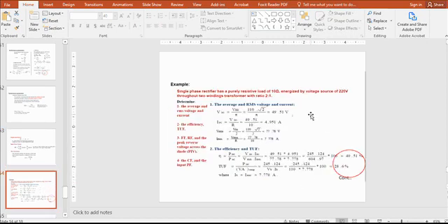Now this is the formula. We can see that the average and RMS values are calculated. VDC is equal to Vm over pi. So this is for the half wave rectifier, and current will be calculated by dividing the voltage by the resistance. We already discussed these points in great detail in class, so I'm not describing this in great detail again. Okay, this is the VRMS formula, Vm over 2, and I will be calculated by dividing voltage by the resistance. So these are the values we got here.